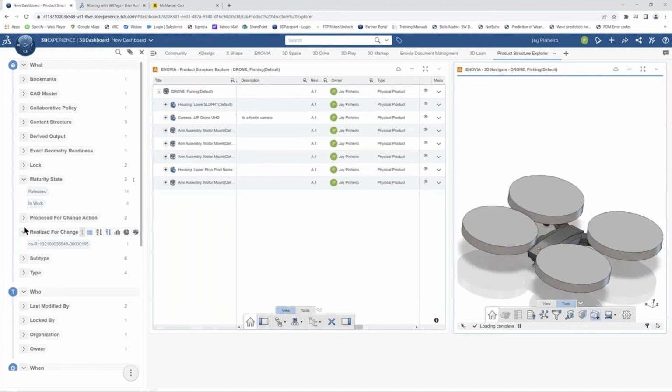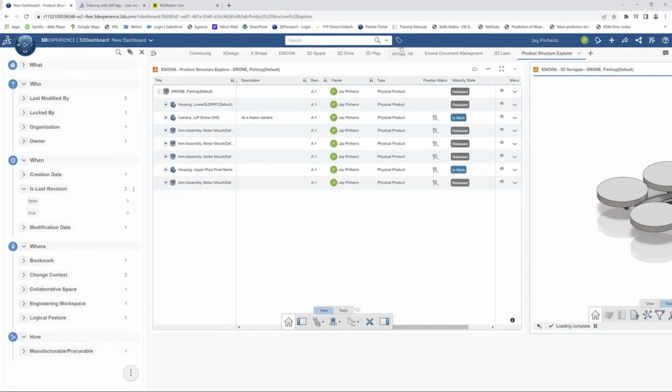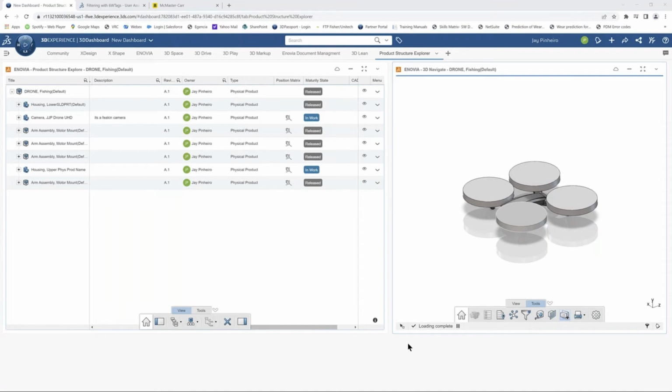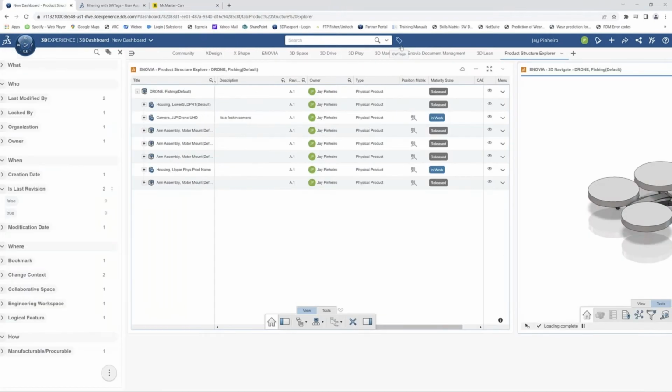The drone itself does not look like it has four pie plates sitting here in the real geometry. If you haven't guessed it, this is flow simulation. When we do a flow simulation on this thing, we take the rotating region and make a nice little cylinder out of it. So when I did my engineering change, I actually ran these things through flow just to have an A/B comparison, because I have access to it, and it was a pretty interesting little study.